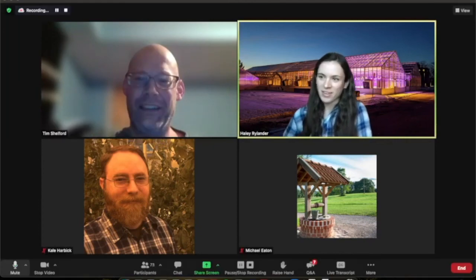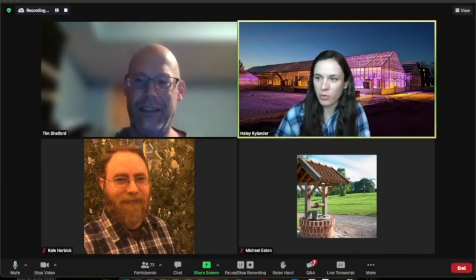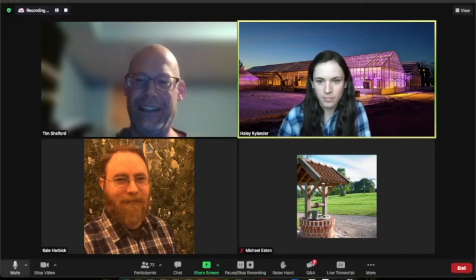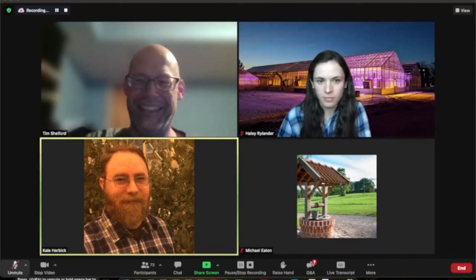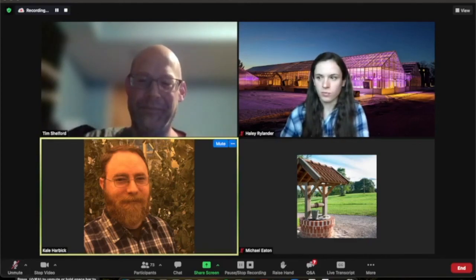Yeah, great. We have another question. So how important are dehumidifiers for the energy balance in CEA? I think this is a big one. So, one number that I like to throw out is if you're growing head lettuce optimally, it would produce something like 4,000 gallons of water per acre per day, every single day. And in a greenhouse, we get rid of that moisture by blowing it out the window. We have fan and pad cooling systems quite often, and we just ventilate all that moisture out continuously or frequently.